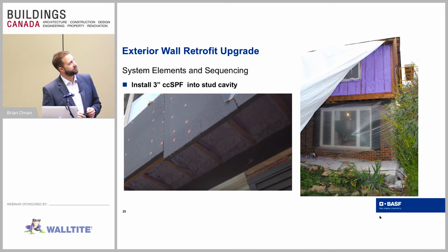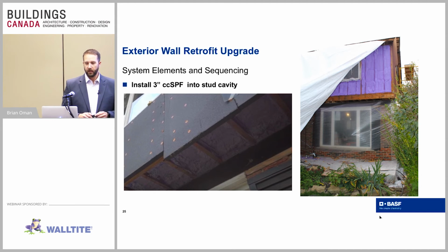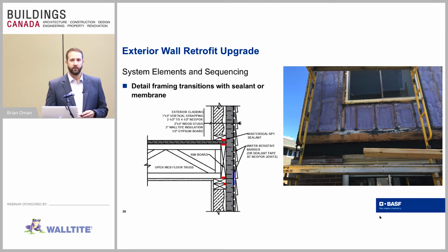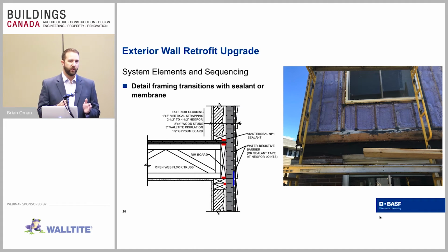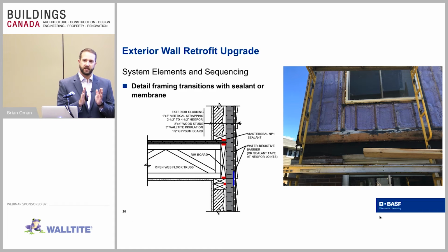So here we can see the foam has been applied, it's been cleaned up here, the studs are exposed. After that, we want to make sure we do that critical air sealing. So the foam has sealed up that cavity. It's expanded into all the little nooks and crannies and all the little voids within the cavity space, but we have all these other gaps. Every time 2 pieces of wood touch each other, we're going to have a gap and a void there, which could allow air and moisture to move through.